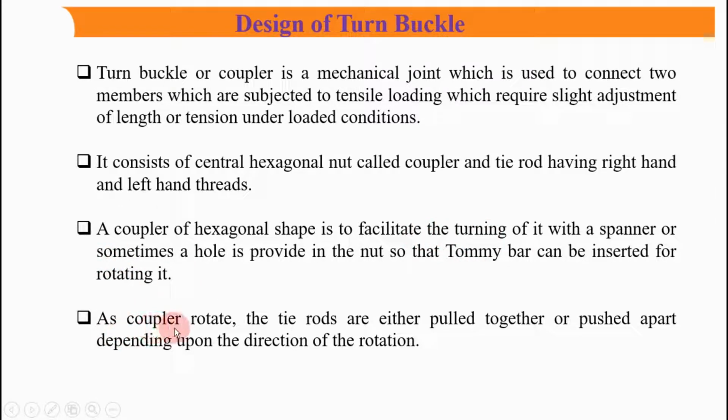As the coupler rotates, the tie rods are either pulled together or pushed apart depending upon the direction of the rotation. If you rotate that hexagonal nut, which is called the coupler, then the tie rod gets pulled, meaning it moves outside of that frame or inside of that frame, depending upon the direction of rotation of